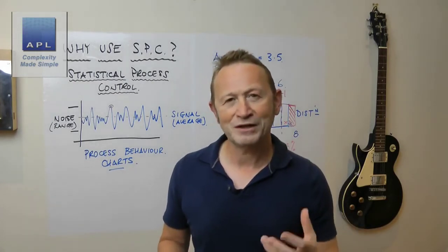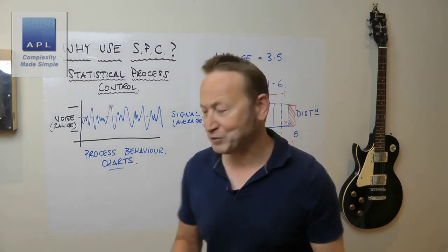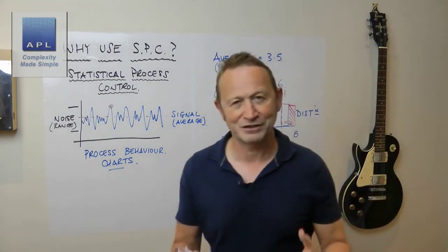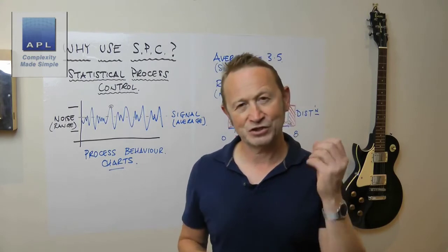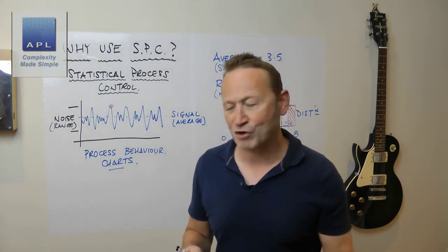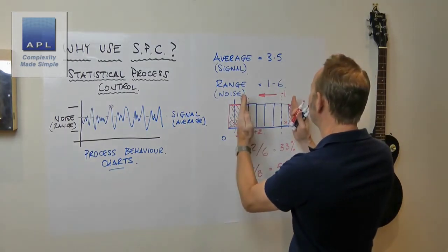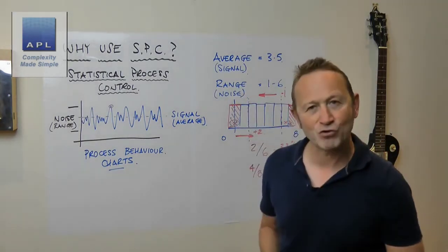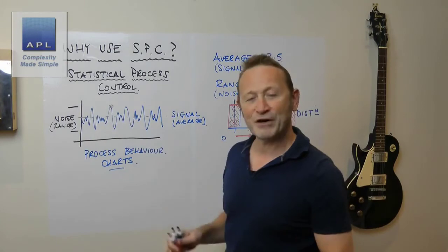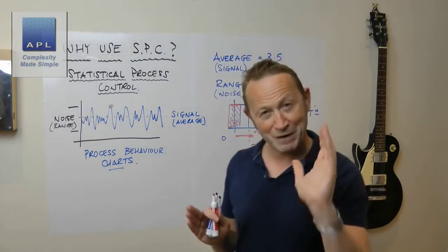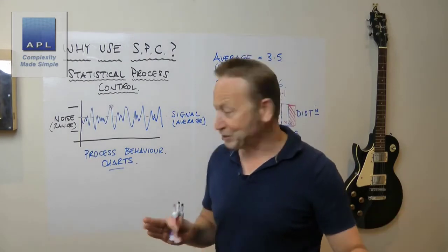And this is what will happen if you don't use SPC. Your defect rates will be elevated if you do not use statistical process control. Because what SPC is trying to do, it's trying to communicate the natural picture. Because of course, what an operator sees is a data point at a time. It's a very bad habit to work to one data point.